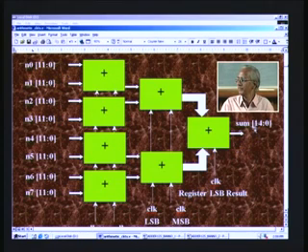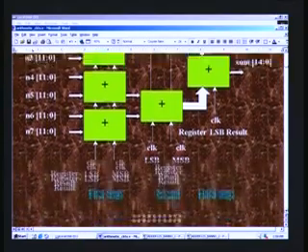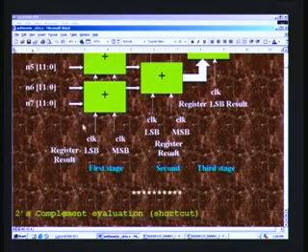and how the 15 bits will be reasoned out right from here. We start with the 12 bits. When you add two 12 bits, it will generate a carry, that means totally 13 bits will be the result, and here also it will be 13 bits. So is the case here. When you add 13 bits, out comes a 14 bits result, and when you add 14 bits to 14 bits, the final output will be 15 bits. That is why 14 through 0 is put here. And this is how we pipeline.